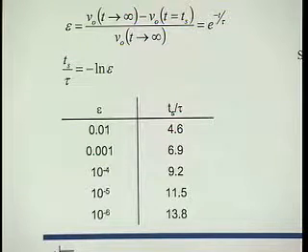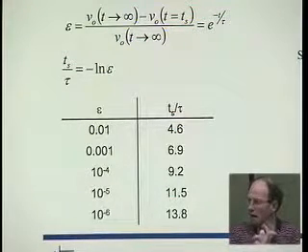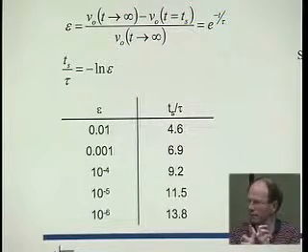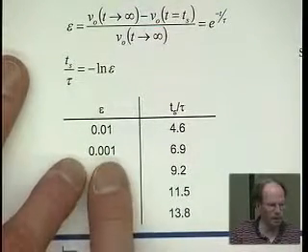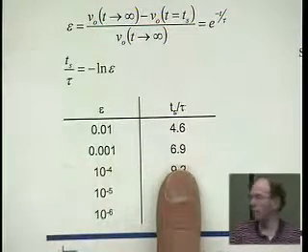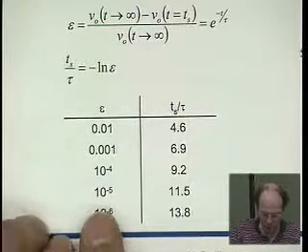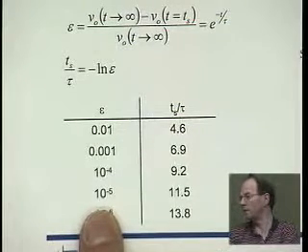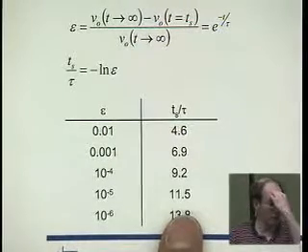Now again, be very careful. We are dealing with a very large number of errors here, and slewing and all of that stuff. Right now, we are analyzing only linear settling for a single pole, no zero. Right? In that case, that's correct. If we wanted to have 0.1% error, then we need to wait about 7 time constants. And if we wanted to have an error of no more than 1 in 100,000, which corresponds to about 16 bits, right? 16 bits is 1 in 65,000. Then we have to wait for 11 some time constants.